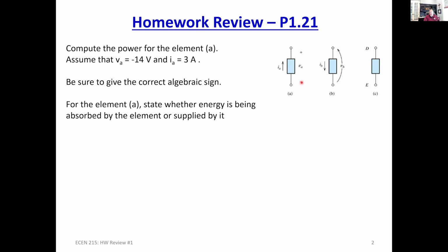That would be our reference, and we're measuring to the positive terminal. So we're measuring from here to here, and that reading was minus 14 volts, which means technically it's backwards. It's actually 14 volts here and 0 volts here. So from a reference point of view, there's more negative potential here.